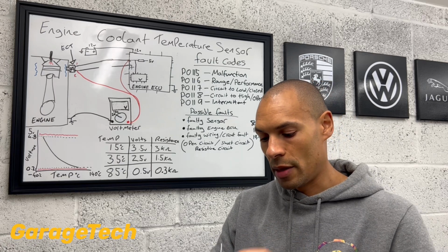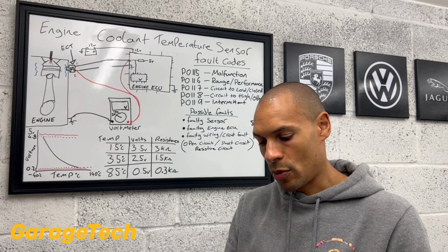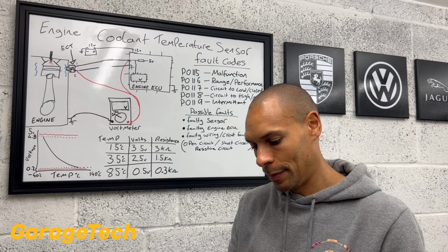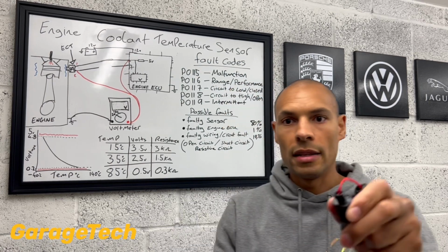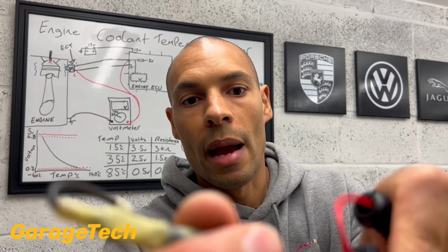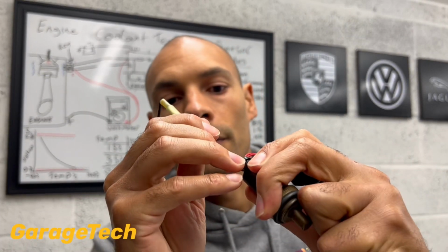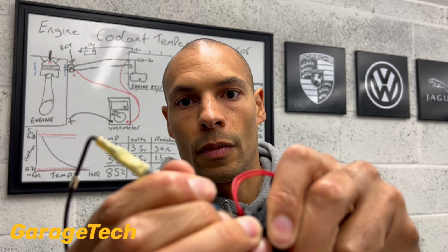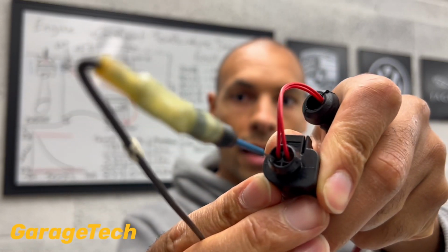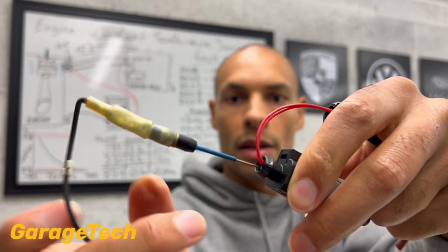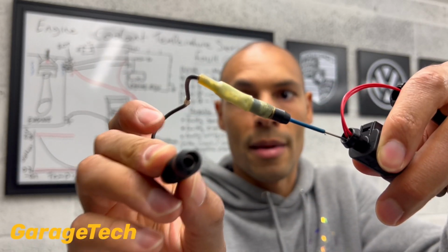You'll be quite gentle with these because you don't want to damage the wiring. Then within the back there, you'll use a back pin like this and just back probe it in. So you're doing that in the back of the actual plug. Okay, and then you use your multimeter in that bit.